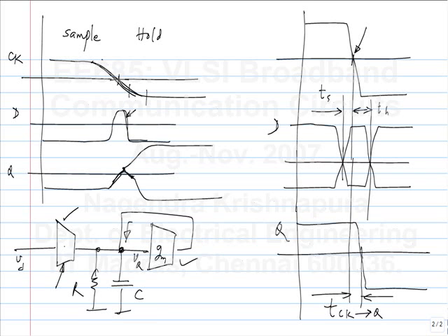Essentially the current going into this R and C, if you take the linear model, will be Gm times Vq plus Gm, let me call this the hold. So Gm of differential pair 5, 6 times Vq plus Gm of differential pair 3, 4 times Vd equals C times Vq dot plus Vq by R. The solution to this differential equation is what you get.